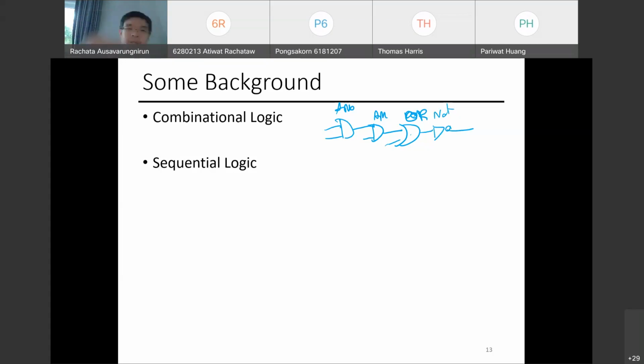What we can assume is when I have the inputs X, Y, C, A, and then the output, with combinational logic, it means that when I have all the inputs, I can assume that the output is that function right away. It's a combination of logic that put together produces an output. This should be done within a cycle. When I have the input ready, I can compute what is my output within a single cycle.